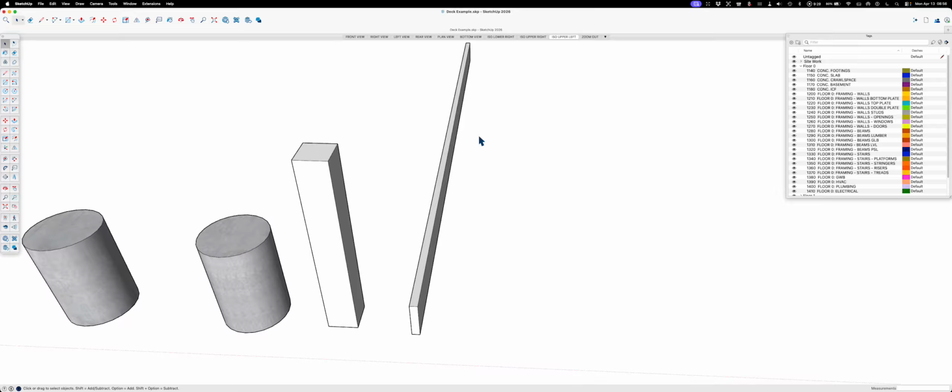So when I made this 1.5 inches by 7 1/4, that's exact theoretical size. A lot of times it's going to be 1 5/8. A lot of times it'll be, especially deck joists, I've seen them 7 inches to 7 3/8 in variation. So that's something you have to think about when you're installing a deck.